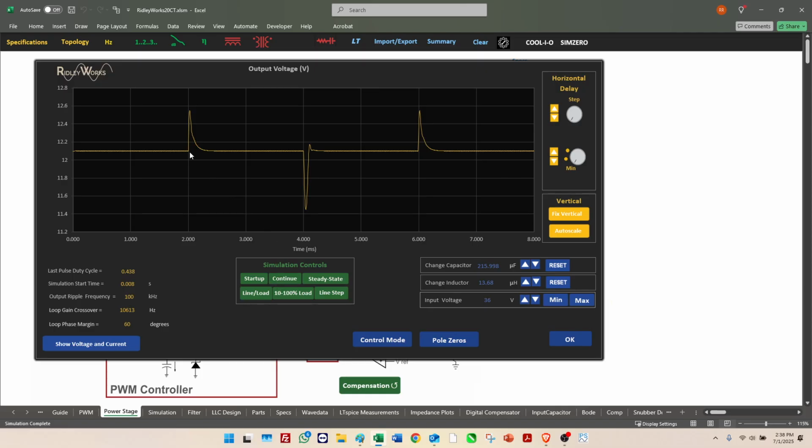So here the converter is stepping down to 70%. Here it's stepping up to 100%. And you can see it's an asymmetrical waveform. You couldn't do this with small signal because it would give you the same result. But on one side you get current limiting, the other side you don't get current limiting. But you do get overshoot of the inductor energy. So if I hit continue again, you can see the first pulse undershooting. And now when you zoom in on that by turning the time base, you can see all the characteristics of that output voltage overshoot.